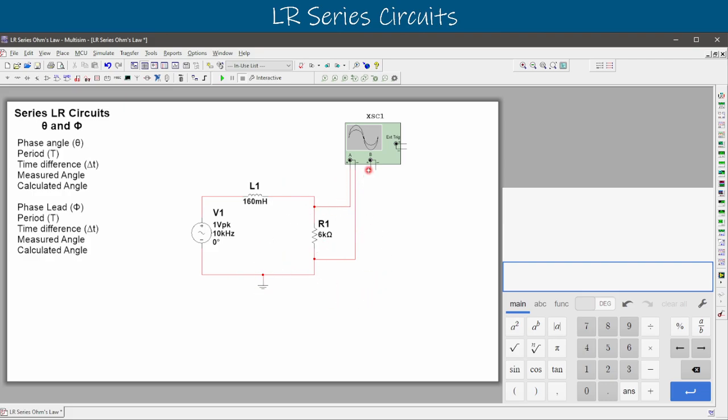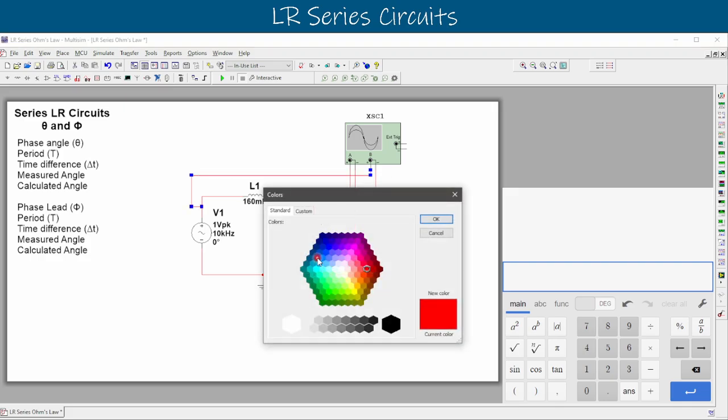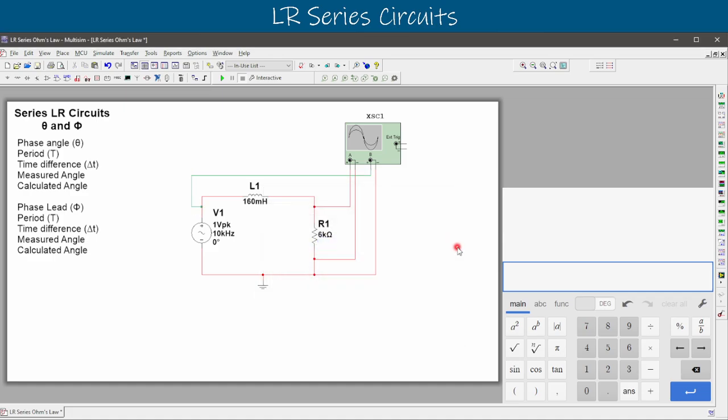We'll take channel B, we'll measure across our source voltage. If we click out here, it'll allow us to keep that bend in the wire. We can click at the front of our source voltage there, and then at the very bottom, the ground location, and that can be anywhere on the bottom ground. Right. So let's change the color of our voltage source by right-clicking in segment color there. We can change it to a green color so we can tell the difference here. We'll OK that out.